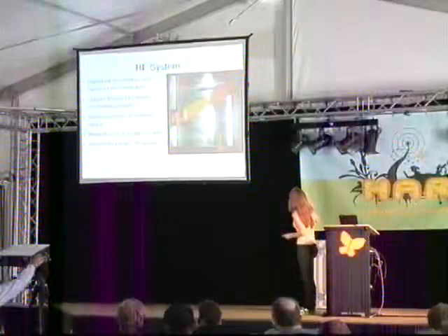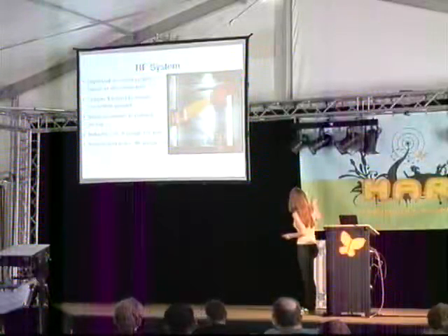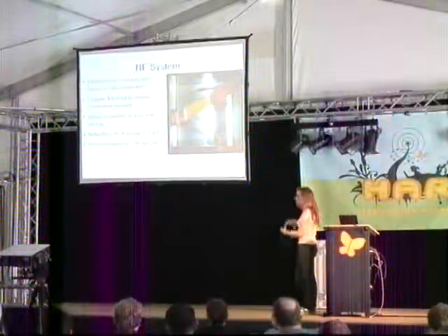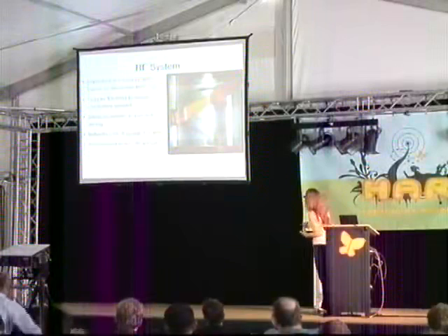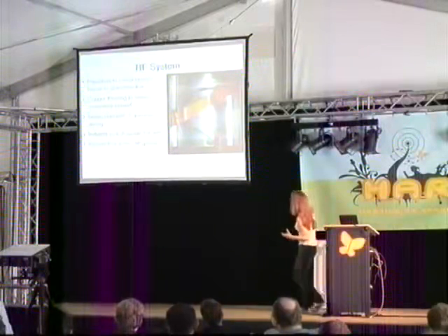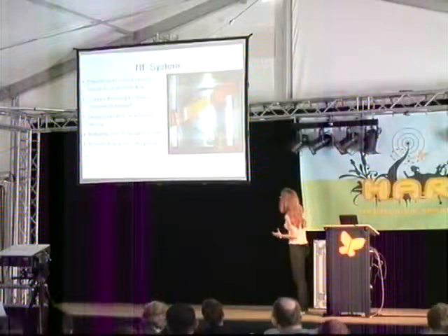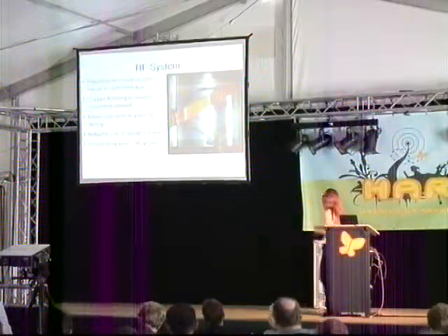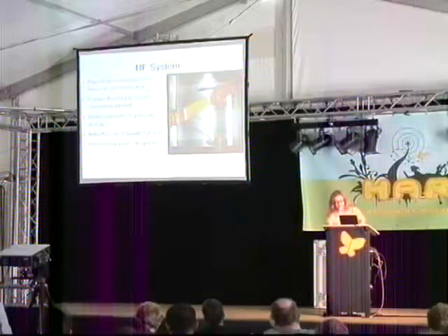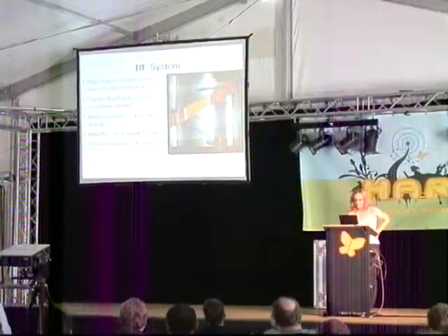Delrin standoffs to prevent arcing. Here are just the BNC connectors to your function generator here and up here. If you just make little standoffs out of Delrin, it keeps the system from arcing. Those, just as an aside, are the gauges of wire I used, but obviously you can change them depending on what you want it to be.